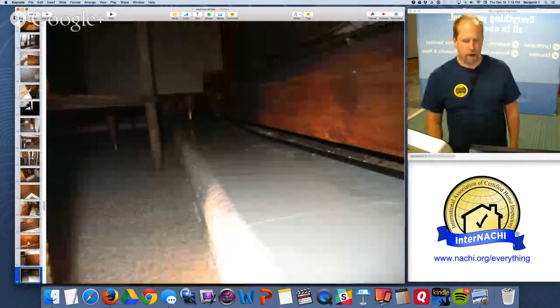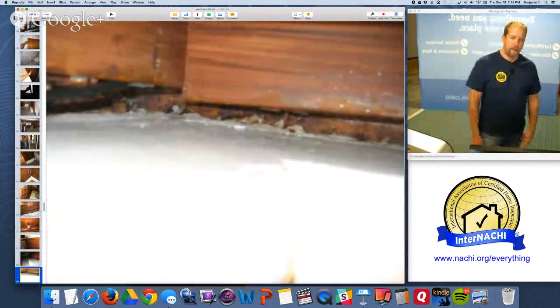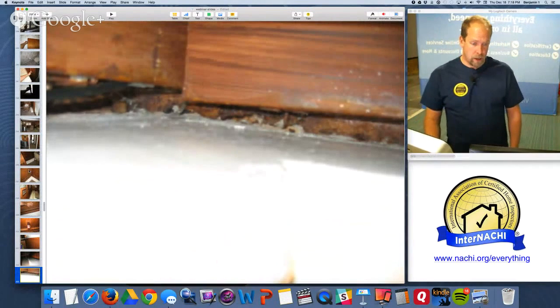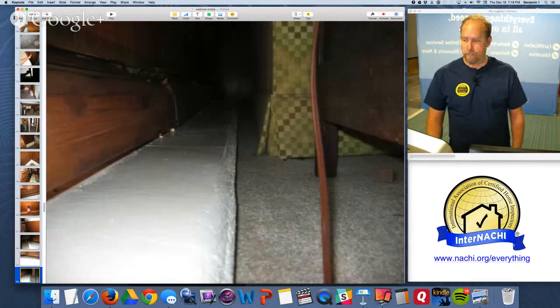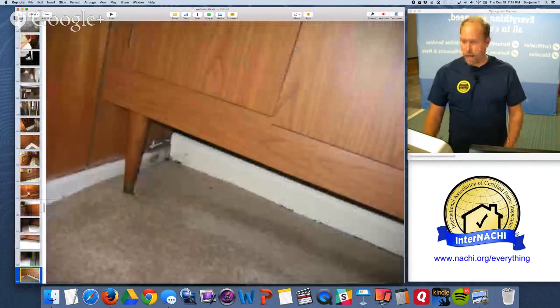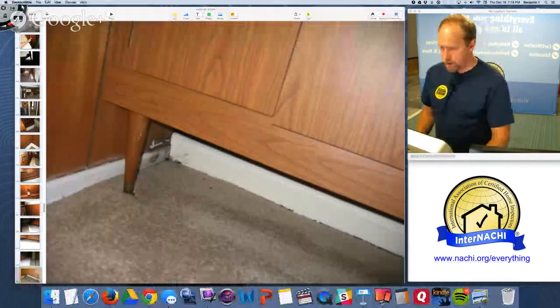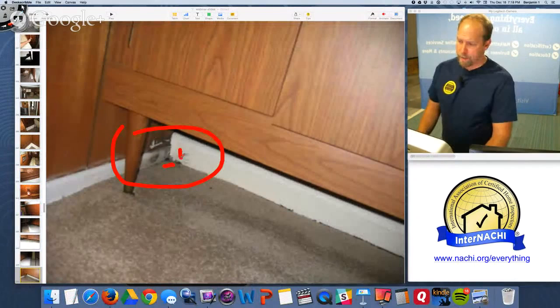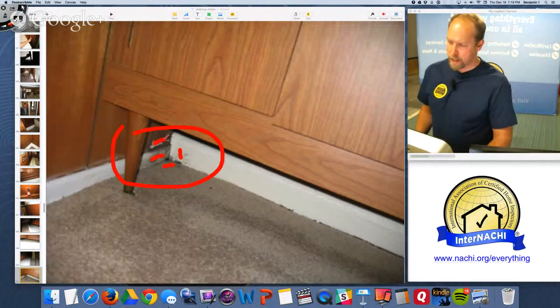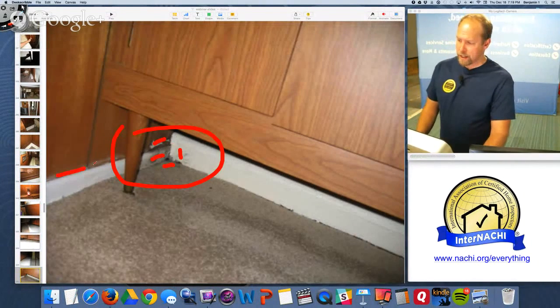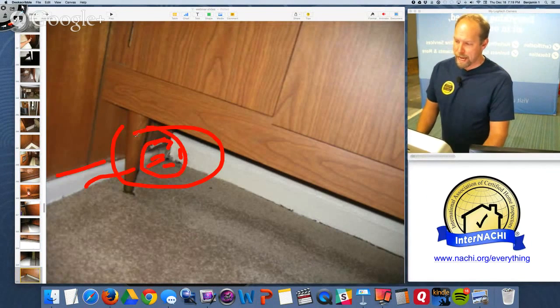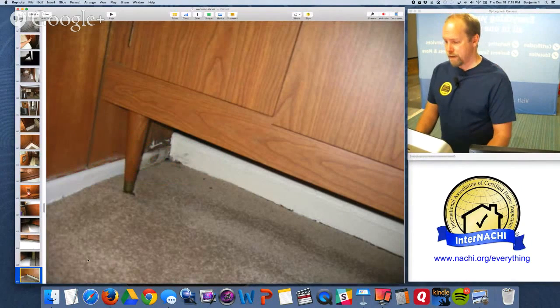Looking for any indications of water now. And there's rust. So that's the baseboard radiator system, and it's totally rusted. So water rusts metal. There's indications of water penetration here as well on several surfaces. The carpet has a stain, the baseboard trim has a stain, this trim has a stain, this wall paneling has a stain. It extends all the way over here. This has been painted over to make it look good, but I think this is after it's been painted. So right now I'm just calling it out as active, right?